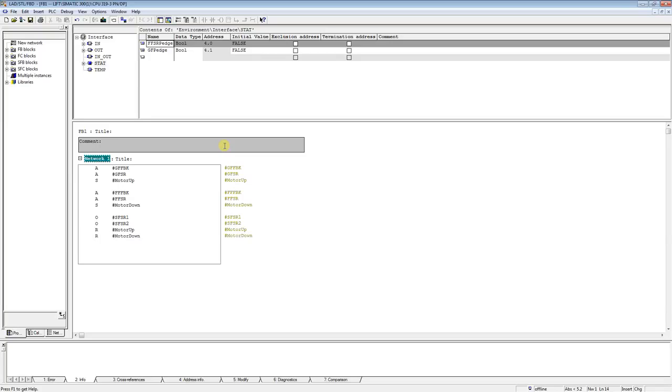And now edges, because we have here in the code detecting of signals without edges. We should use edges in the next part of the program to properly detect when the lift is actually at the sensor first floor or sensor ground floor.